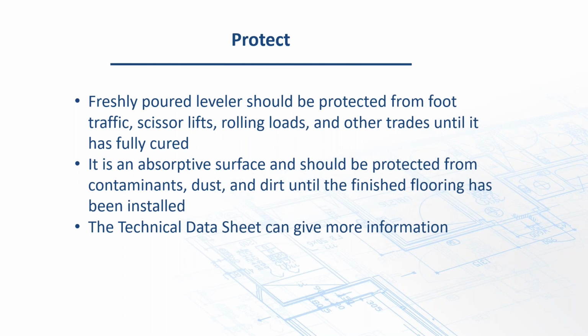Certainly scissor lifts and so on. If you do have to get them on there early, protect them with plywood or something that's appropriate. And try and keep other trades off until it's completely cured. It's an absorptive surface, so it can contaminate fairly easily. Like I said, overspray from the paint will do it. Dirt and dust, you don't want the drywaller in there sanding the hell out of stuff the day before you're going to go in there and start installing tile.